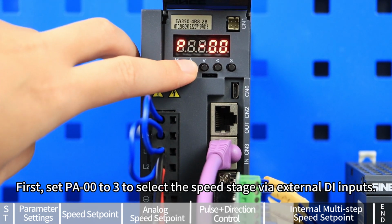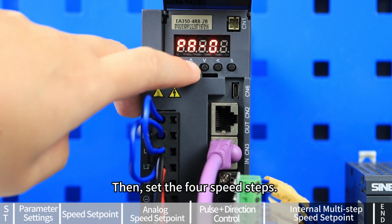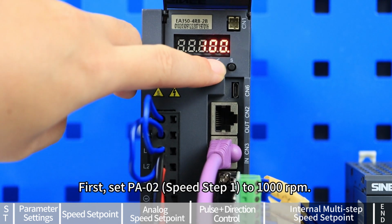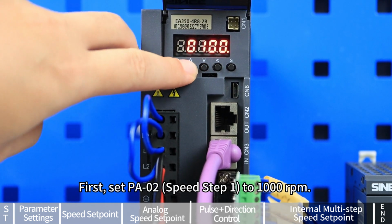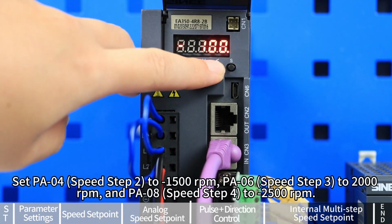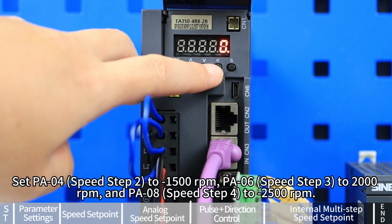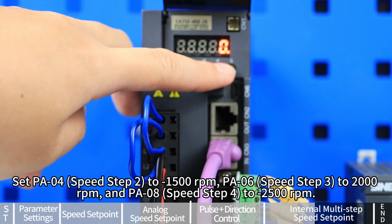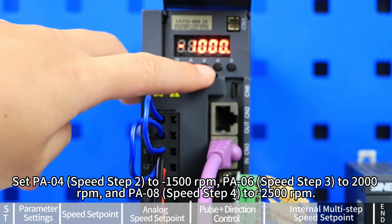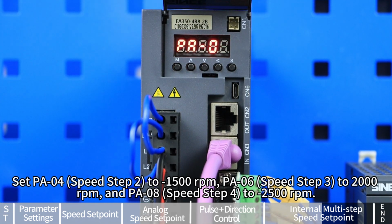First, set PA00 to 3 to select the speed stage via external DI inputs. Then, set the four speed steps. First, set PA02, speed step 1, to 1000 revolutions per minute. Set PA04, speed step 2, to -1500 revolutions per minute. PA06, speed step 3, to 2000 revolutions per minute. And PA08, speed step 4, to -2500 revolutions per minute.